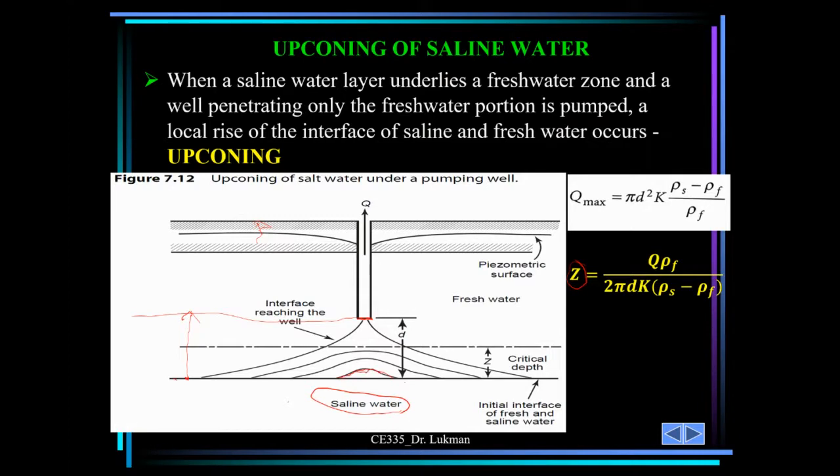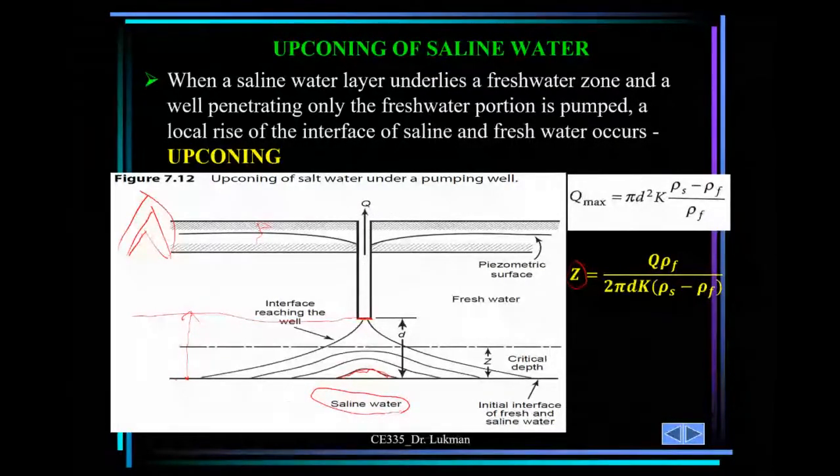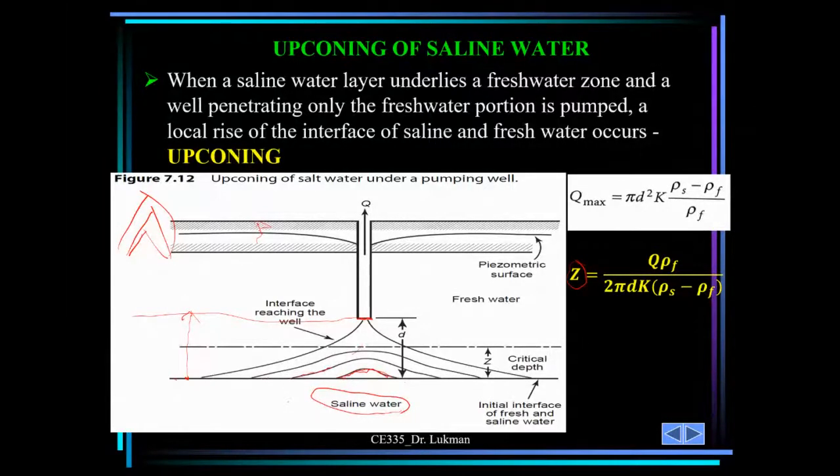You can see that is upconing. Cone is something like this. This is a cone. So upconing, it is increasing. When you are still pumping, this interface will be moving up till a point whereby it can move into your well.